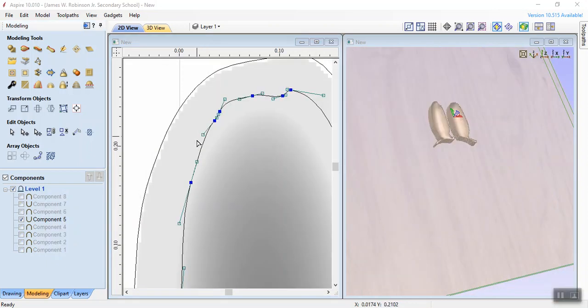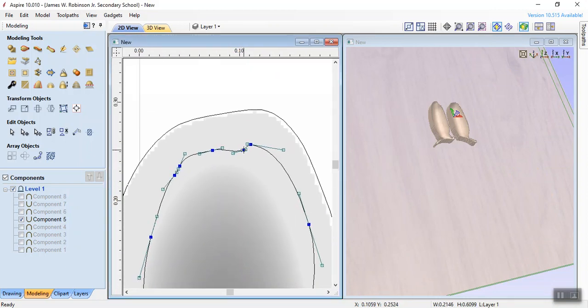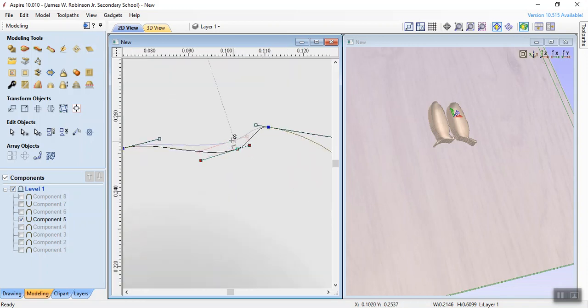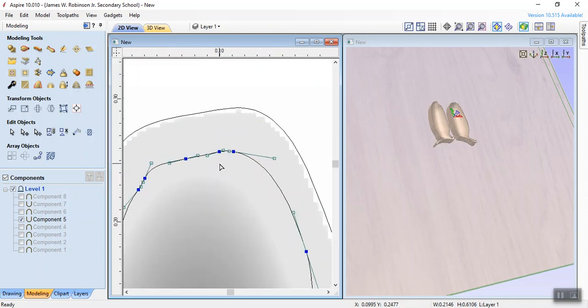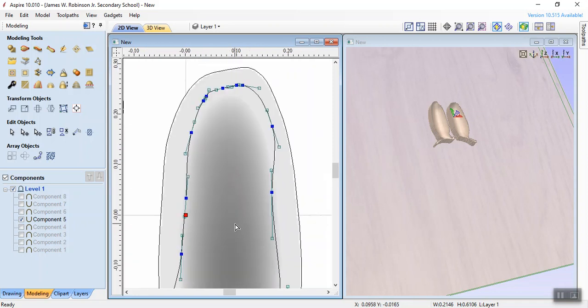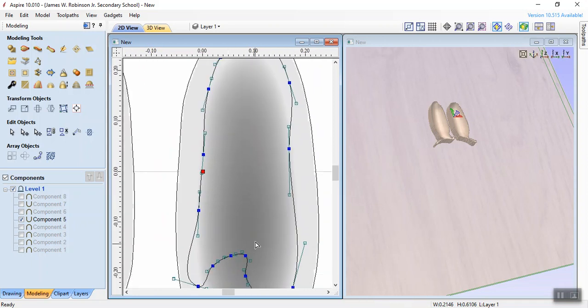One of the ways to modify the lines after they're created is, when you click on the line and press the right mouse button, you choose the Node Edit option. The Node Edit option will enable you to change the line by simply dragging from place to place at higher precision. This is an important part.